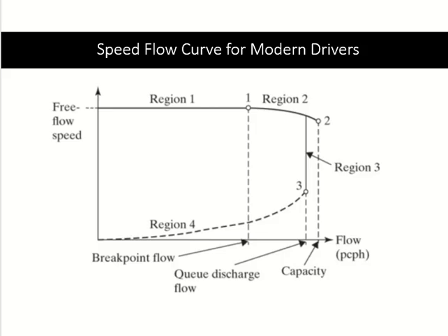This is your threshold, the end of region 1. And they are calling it the break point. We will use these points in another lecture, and that will come after many days, so you will forget it, I know. But just fulfilling my duties. So this is the break point, your threshold after which you will not maintain your speed. Got it? Then we reach this point. This point is the maximum of flow. The maximum flow is called capacity.